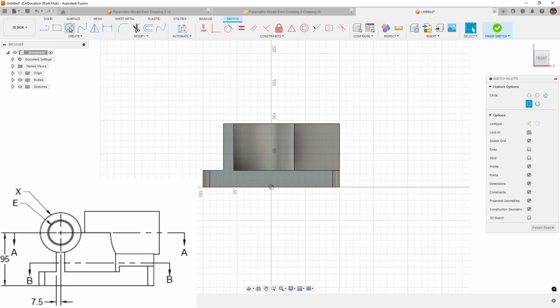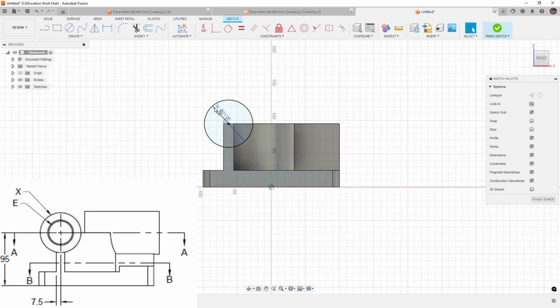Now, the way that I'm going to do this is as a solid, and I'll come back in a secondary sketch and remove the inside. And the main reason for that is because the vertical rib that we created is going to potentially cause a problem with this. Now, we have to remember as we're looking at this, on the detailed drawing, that bottom left view, the outside diameter here is value X. So we need to make sure that we are referencing the correct value.